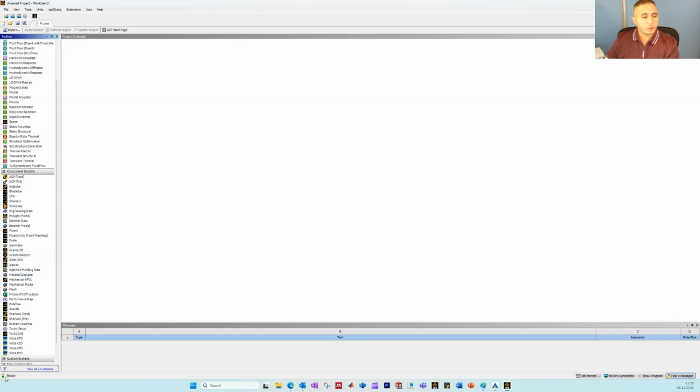You can look also down far on the bottom left hand side here. You can see that green icon in there, and this green icon is telling you Ansys is ready to do any work, or the workbench is ready to do any job that you're asking it to do. And sometimes this status icon is red, and if the status icon is red, then you cannot do anything until Ansys or the workbench finishes the work that it is doing.